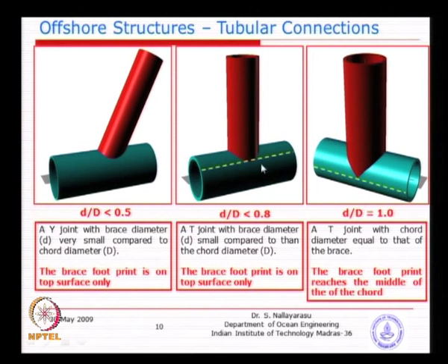Try to limit it to less than 0.9, 0.8, and when you have such a situation, you actually have the stress concentration here will be very large because of the welding singularity. So, you need to understand the configuration before designing, whether you should go this way or the other way, the results could be different.